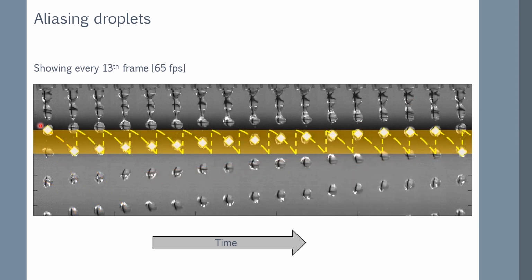Okay, so if we look at the strip again, the sawtooth is the true waveform, but the samples give us this waveform that looks like it's actually moving upwards, or the direction is wrong. And this is what happens when you're sampling. You might sometimes get the direction wrong, and in this case you get both the direction of the phenomenon wrong, but also the frequency wrong. So the frequency is actually very fast, but you're seeing this very slow wave. So this is like the slow motion effect that you get when you use a strobe light.